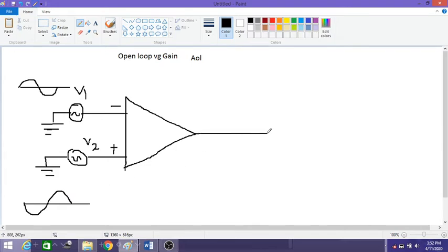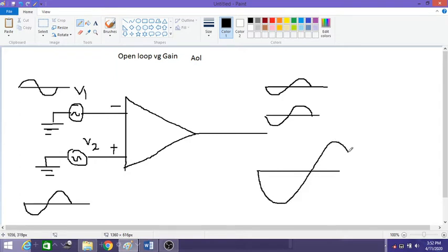So what happens in this case? Since this is connected to the inverting terminal, the voltage appearing across it changes internally by a phase shift of 180°, and this is added with the voltage V2. Finally the output voltage is an amplified version of the sum of the two inputs. This added input is multiplied with AV, which is why it is called an open loop voltage gain.